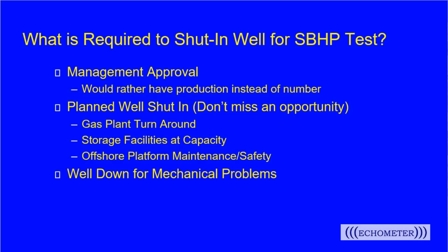Or if the well's even down for mechanical problems, that would be a good time to get a static bottom hole pressure. I've often told people that if the well was down for a mechanical issue like a rod part, and it was going to be several days before they could get a pulling unit out there to fish the rods and repair the issue, that might be a good time to get a static bottom hole pressure.